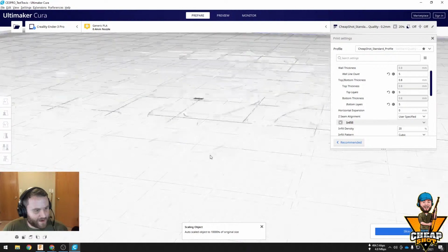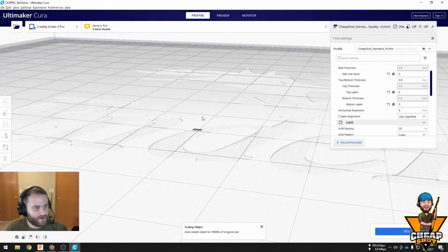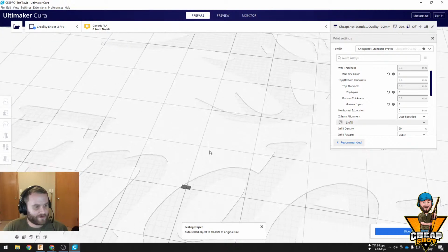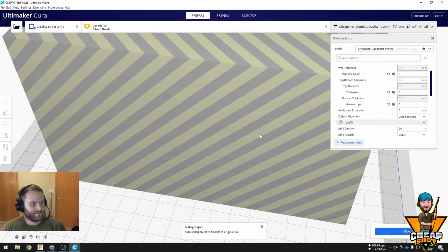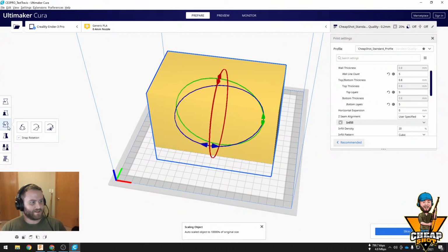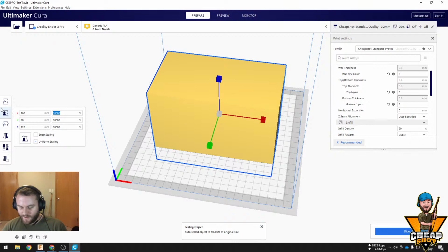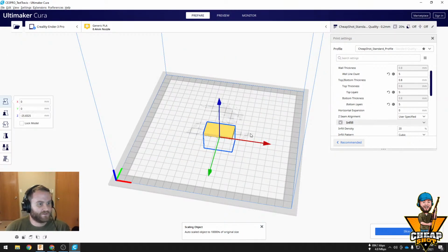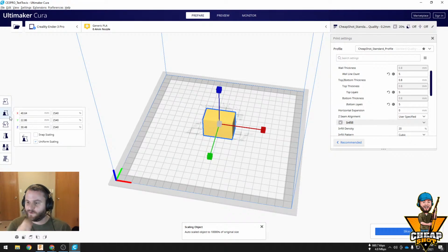All the way down there. There it is. Well, I actually think it's up above. I don't know where it was. But what you're saying is it's basically not the size it needs to be. How do you fix it? Scale by 2540. That goes from inches to millimeters, and it's great. It's right there on your keyboard.